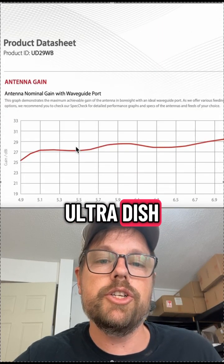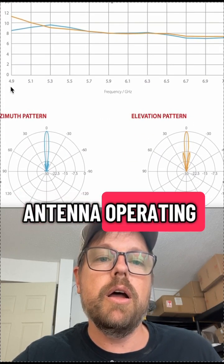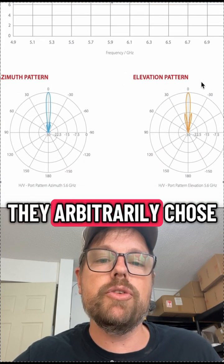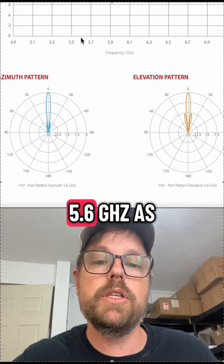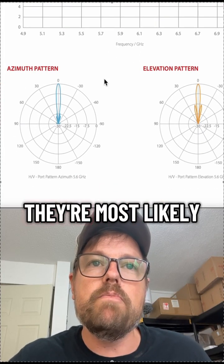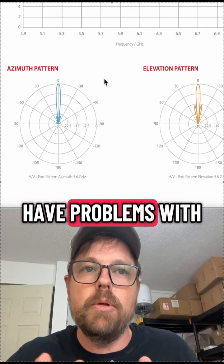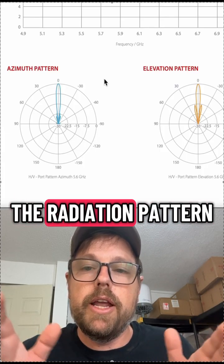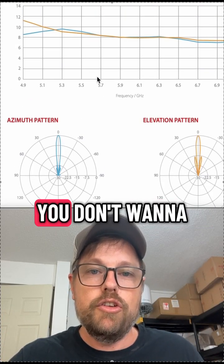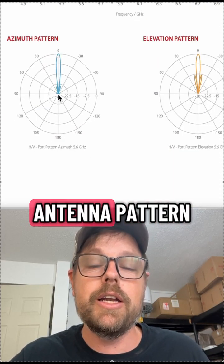This is the Ultra Dish. This is supposed to be a wideband antenna operating from 4.9 to 7.1. They arbitrarily chose 5.6, that's the frequency point. But with antenna patterns, they're most likely to fall apart on the edges. That's where you're most likely to have problems with the radiation pattern, with side lobes manifesting. You want to see the edge cases. You don't want to see a cherry-picked value with a hand-drawn antenna pattern.